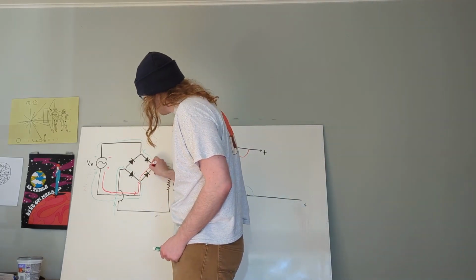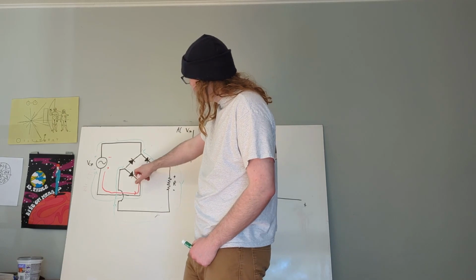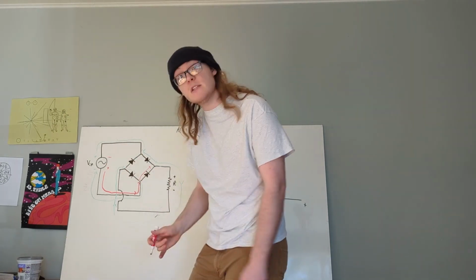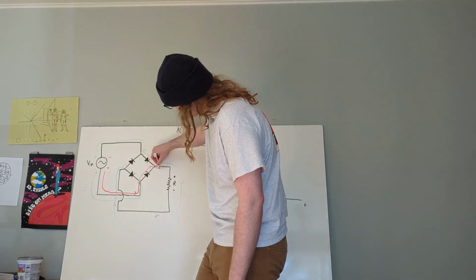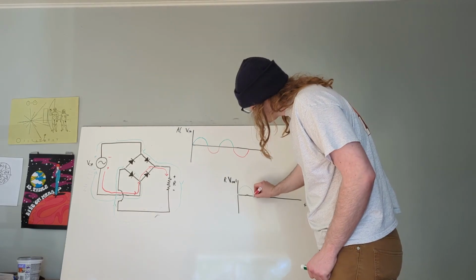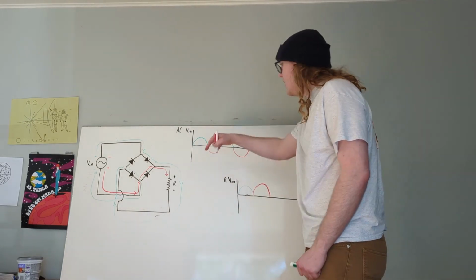We'll flow into this next junction here, where we can again see that the current direction is blocked by going in this direction and easily back into our voltage source, and thus must flow across our resistor. We can track this current into the resistor, and notice that it's coming into our positive side and inducing a positive voltage across this resistor.